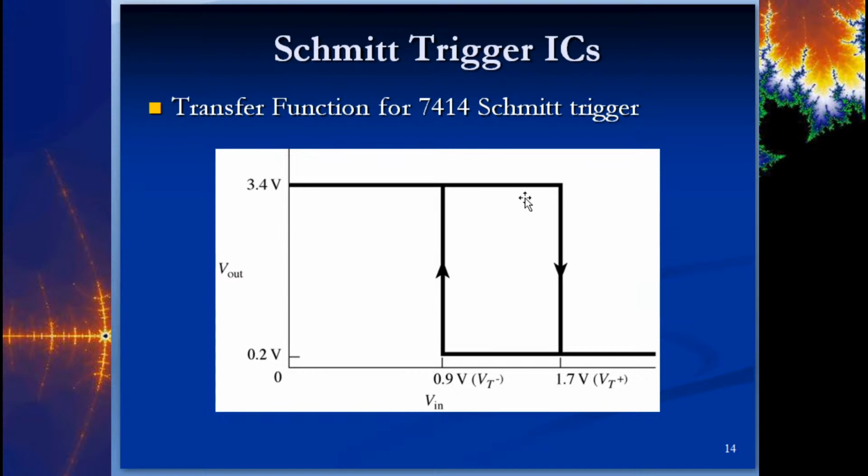So anyway, this is what the transfer function would have looked like if we had done Lab 9 face-to-face. You would see that the Schmitt operates like this with a hysteresis, whereas the TTL is more of a waterfall. And the CMOS almost looks like a straight line, like a slope, not a nice curvy waterfall. But the Schmitt, again, has these nice crisp lines, and you also account for some of that error.